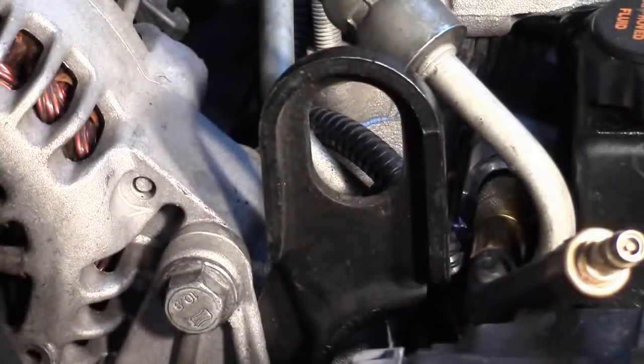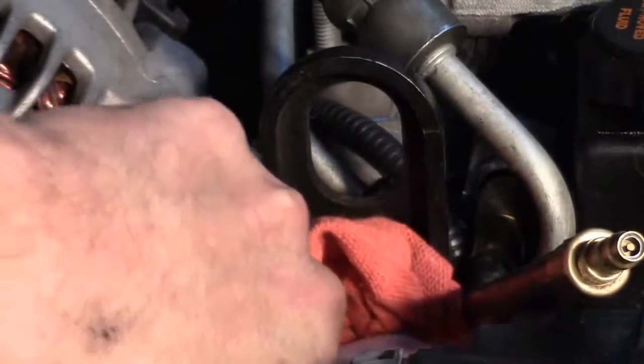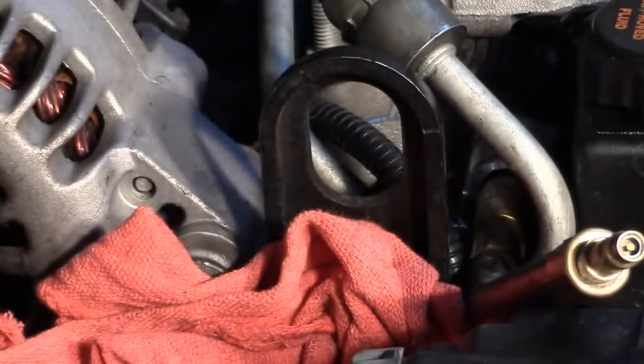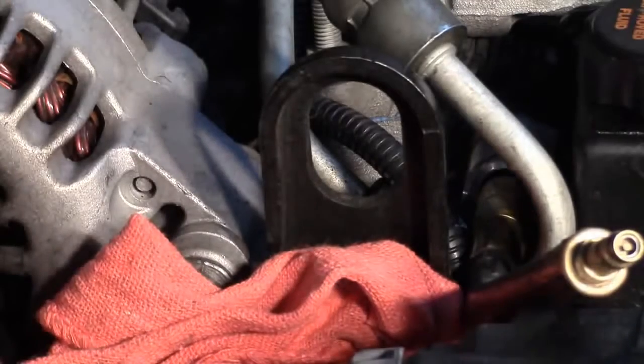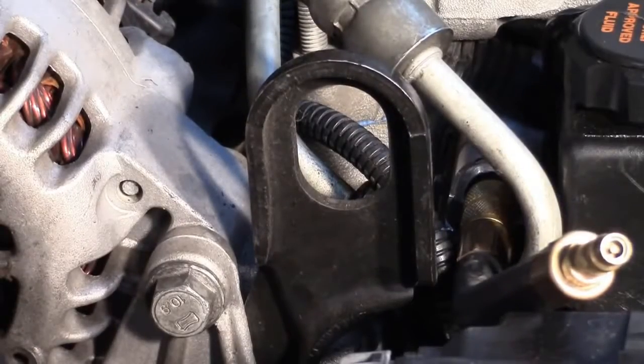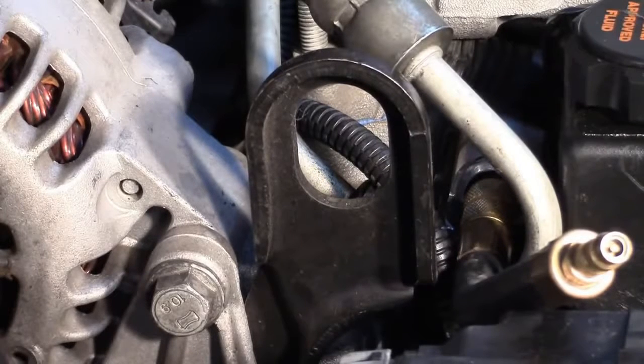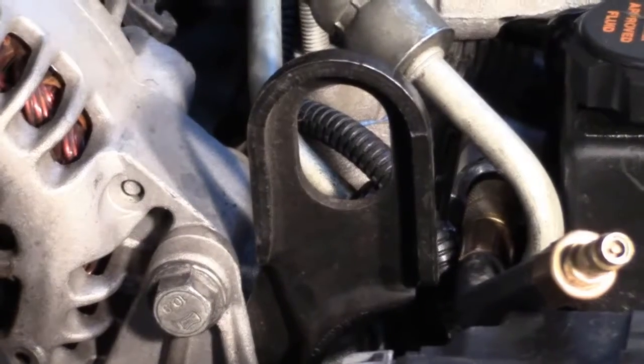You always want to be really safe with that, especially on vehicles that don't have a Schrader valve, where I have to rig some connection to tee into the fuel feed or something like that. That definitely can get a little messy. One of the best things to do is to pull the fuel pump relay or something like that on the car to run it dry to relieve the fuel pressure. Typically what I do is I just depress the Schrader valve and catch the fuel with a rag. That's just fine. But you want to make sure you're not around any open sources of flame, like your garage heater if it's winter. Obviously we're doing fuel stuff here, so safety comes first.